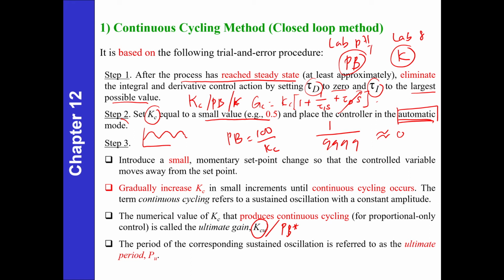Without that, we cannot determine the correct value, and without knowing that, how would this tuning process end? Forever, because we never know. That's why they designed it like that. Don't think too much, it's just a step. Simply put, tuning is finding the best values of Kc, tau_I, and tau_D.